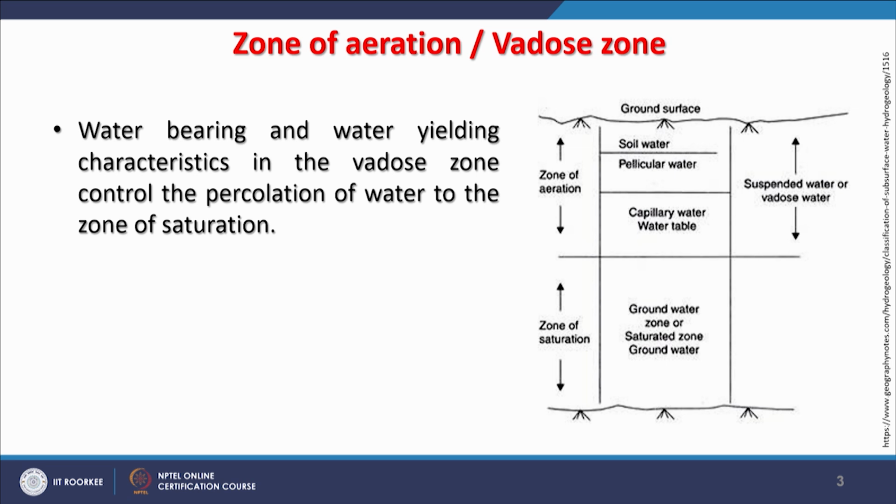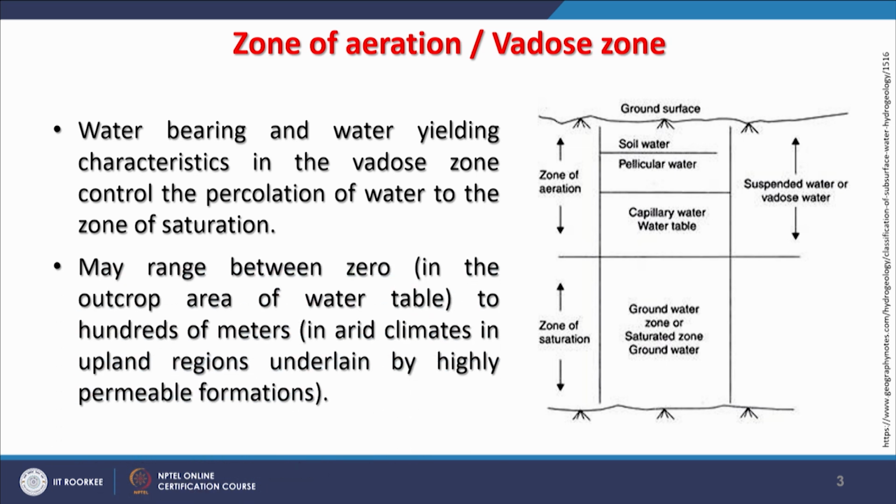Whenever there is rain, the initial process is infiltration, and later on, when that infiltrated water goes downward in the pellicular zone or capillary water zone, that process is percolation. So, there are two different things. First infiltration occurs, then percolation occurs, which makes the zone of saturation rich, and the water table may go high because of better percolation of rainwater.